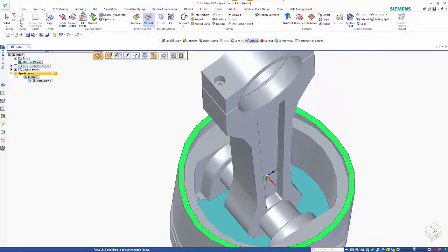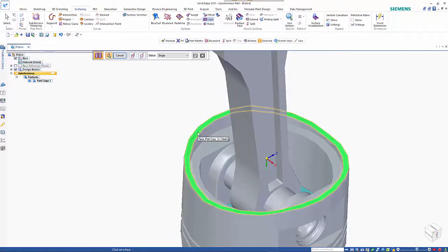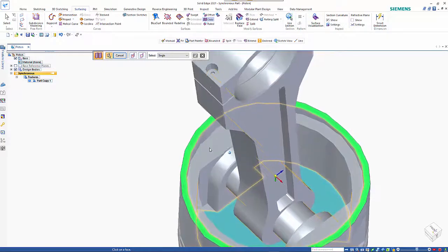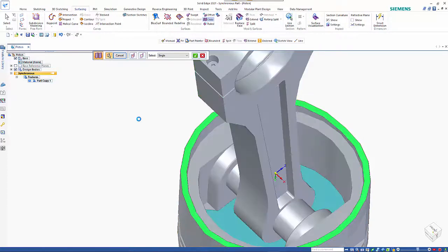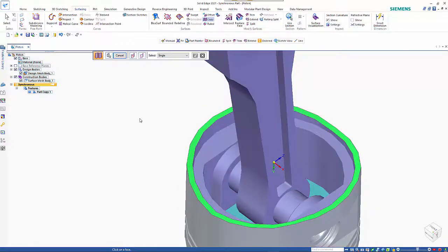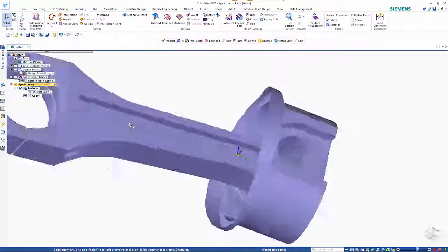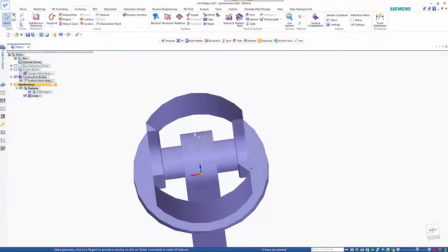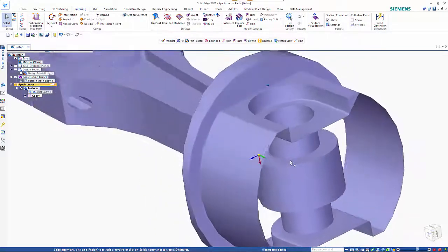So if I go into surfacing and go copy, you can see that I can pick up on that surface that we've created, but it also means that it's going to allow me to take this area in here. If I hadn't done that, that would have selected the whole model in its entirety. So if I just pick on that, you'll see that we can end up with a copy of those mesh surfaces, and that then gives us, because we've cut out this bottom face, the access into defining the areas that we want down the bottom here.